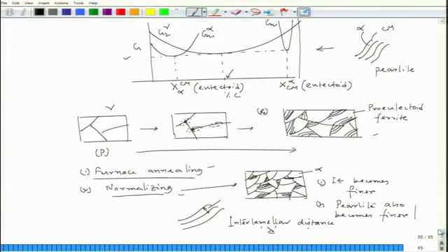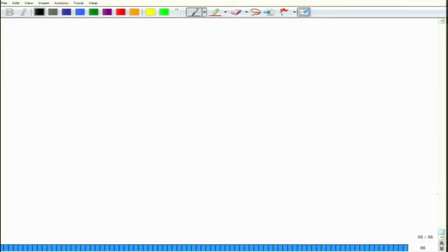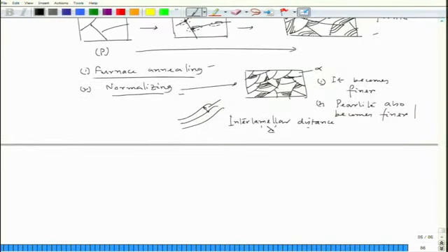But if I go for water quenching, then I would have an entirely different picture, because the phase that would appear is called martensite, and that morphology is also entirely different. So, now from our discussion it is very clear, for example, if we do quenching, that means I take it to austenitizing temperature, I form entirely austenite, then I take it out from the furnace and put it in water kept at room temperature.